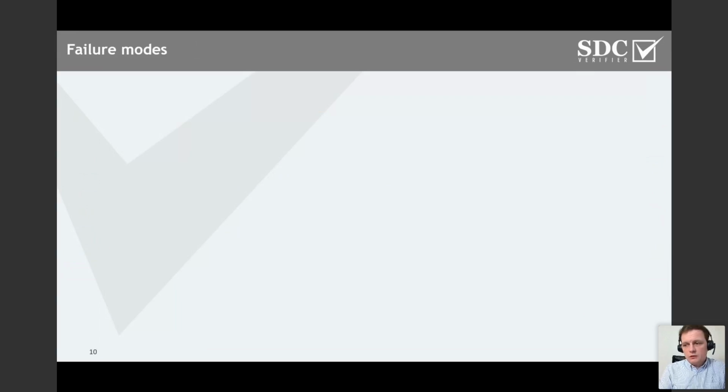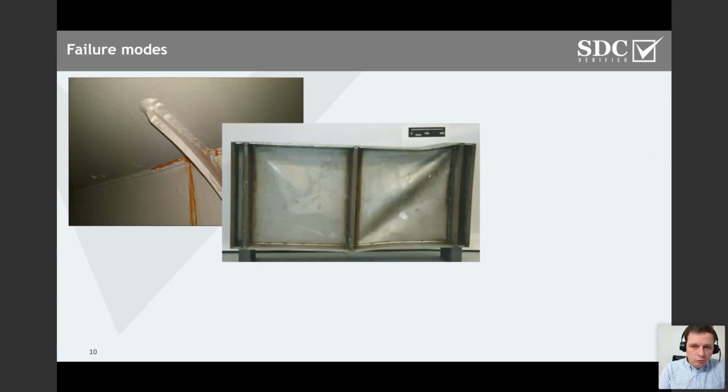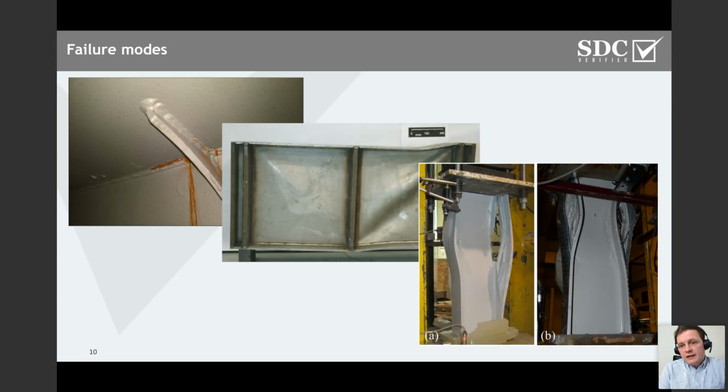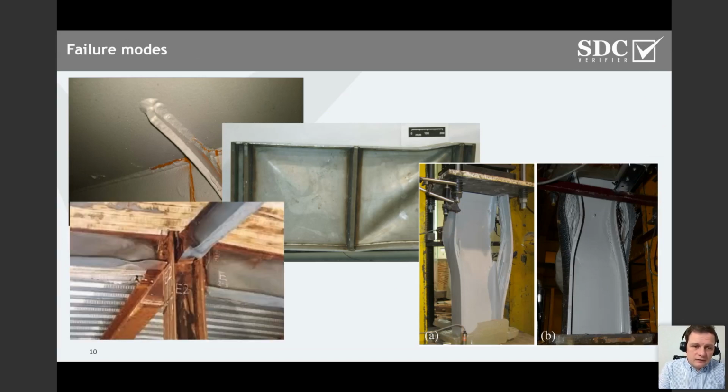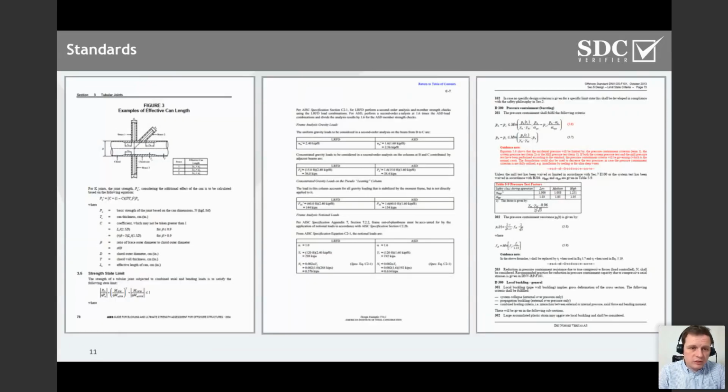And this helps you to prevent certain failure modes which you do not necessarily see straightforwardly based on engineering judgment, your knowledge or past experience. So you have a certain set of outputs, but to make sure that your model is safe enough against fatigue damage, that it's not going to buckle, both in terms of plates or beams, that connections are going to stay intact, and that there is not going to be damage to the connections, both bolted connections, welded connections, and all types of fancy joints, you need to comply with requirements and with the formulas of the standards that are prescribed in the documents by someone doing this check and comparing it to the reality before you.